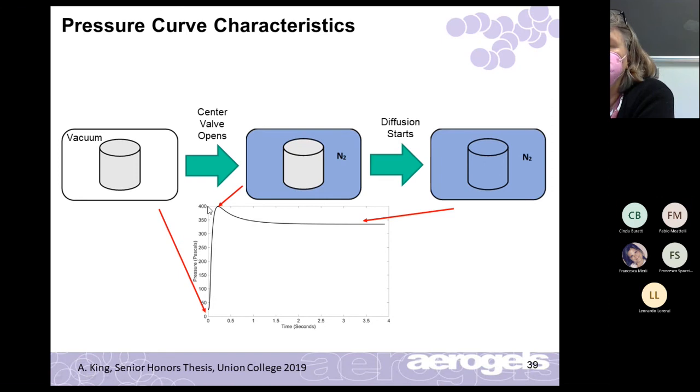And so you can solve the differential equations that describe that diffusion into the material. We do a 2D solution with this because we have a radial direction and an axial direction. But what we really want to do is 1D, so we're trying to make some aerogel spheres.